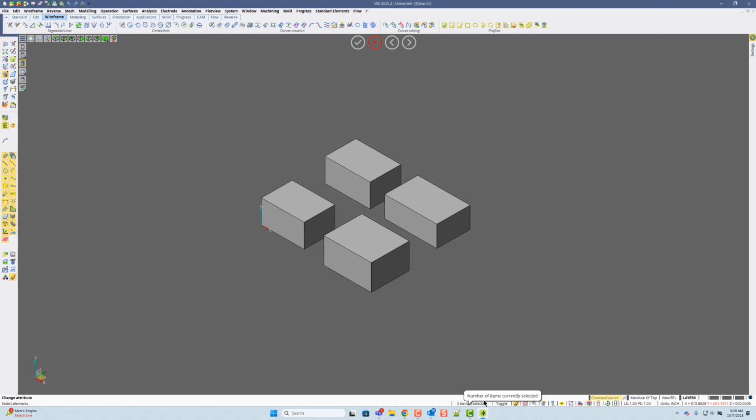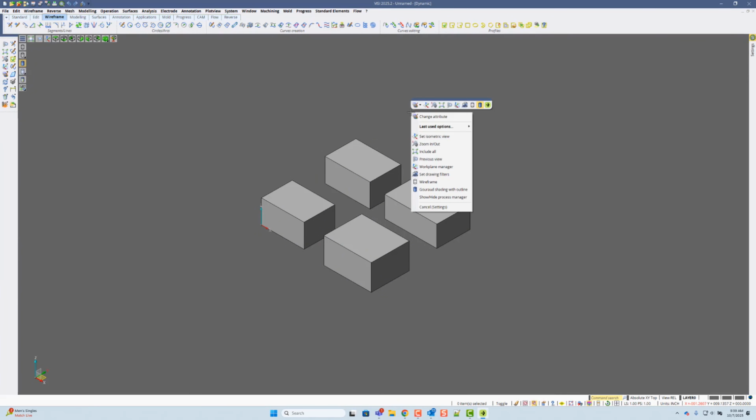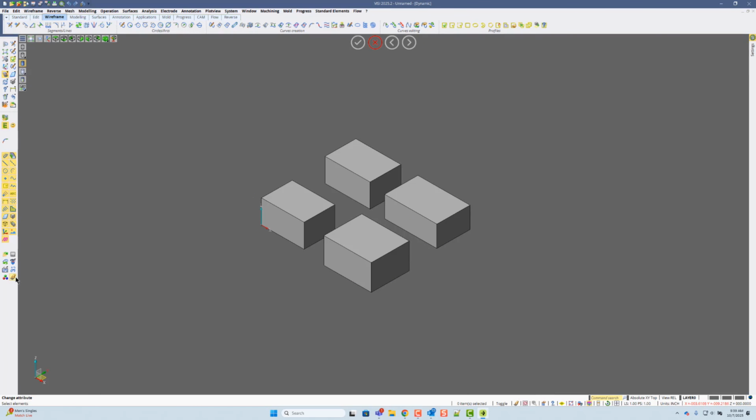There's a couple selection modes for block control down here. This one right here, you can turn on and off block control. See how it's turned on inside the command. If I deselect it, get out of this command and go back into it, it is no longer selected in there. So if I select it again, turn it on, go in the command, you'll see that it's selected now.